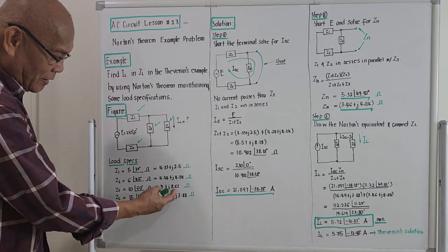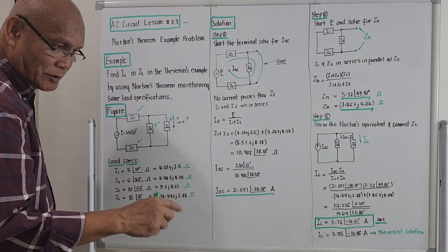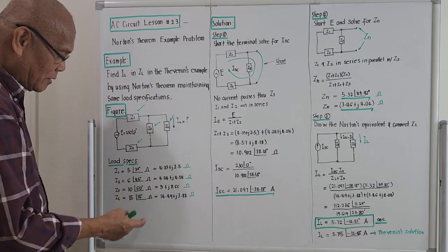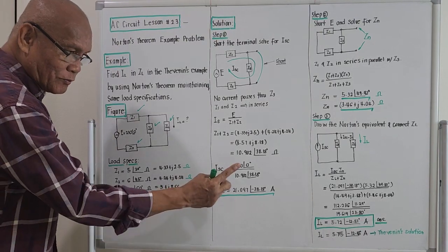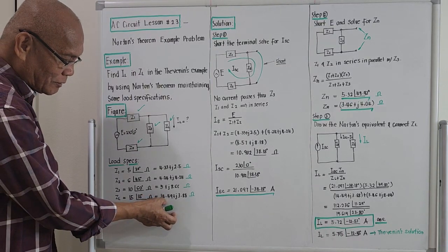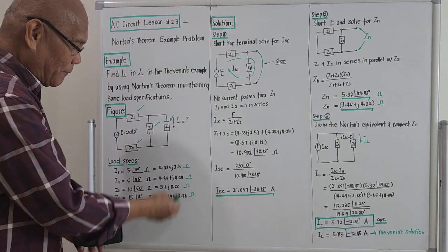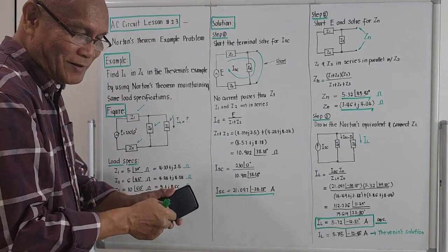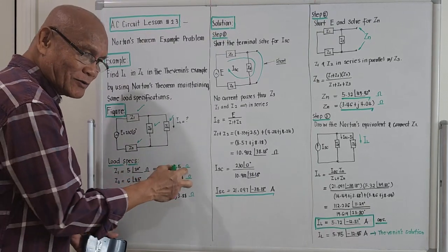The imaginary part should be higher because 8.66 divided by 5 is more than 1. And the arctangent of a ratio greater than 1 is actually greater than 45 degrees, and it is 60 degrees. 15 angle 15 degrees, the imaginary part will be small compared to the real part. So 15 angle 15 is 14.49 plus j 3.88. That is just a part of the solution. We prepare this one, so when we go to the solution, we don't lag behind with changing from polar to rectangular. We'll do it immediately, okay?